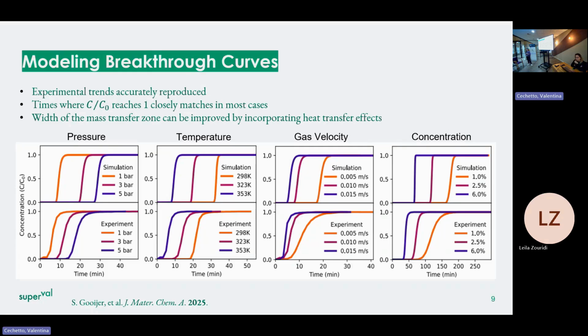Maybe it's also good to take into account kinetics, because kinetics can also depend on the flow rate. Maybe that's why you have a discrepancy between the models and what you have seen before when we tried to do breakthrough on powder. Check kinetics on powder: the powder bed itself also influences the kinetics of the uptake, depending on the size of the bed, because you have diffusion to the surface and diffusion through the material. So if you see differences in breakthrough curves, it could also be due to that. Yeah, that's a good point. Thank you. Any other question?